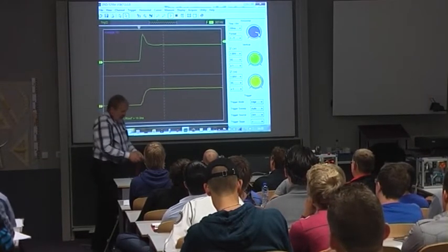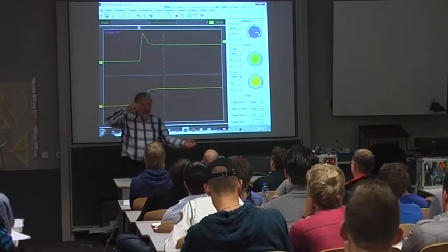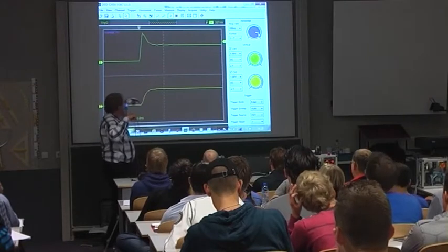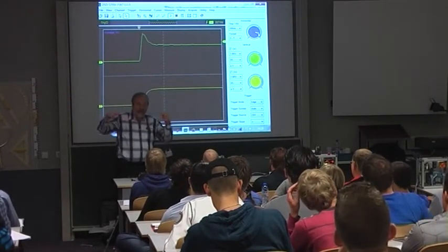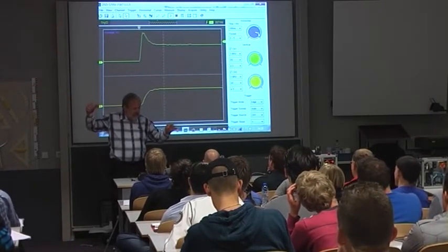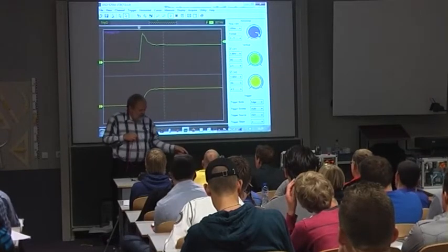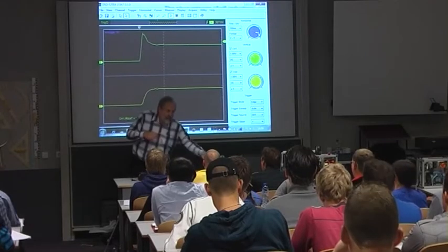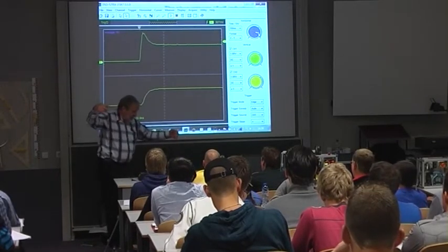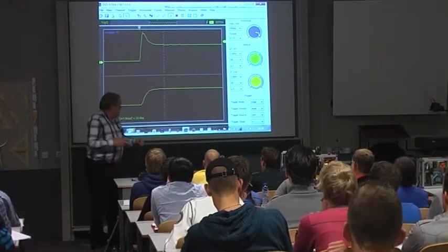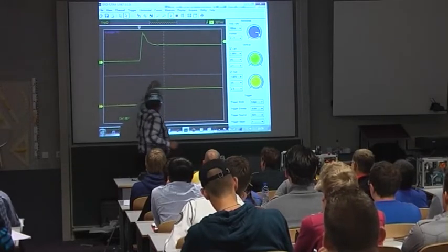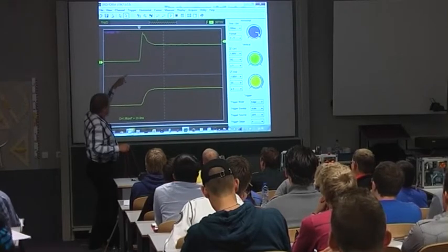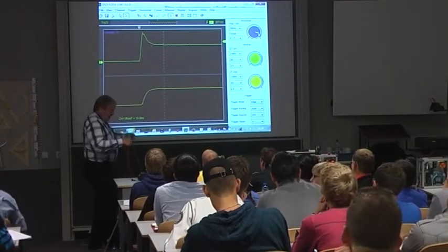Now what happens here? Okay, this square wave is in this case a 3 volt peak square wave. Put it on a wire. In the generator there's a 50 ohm resistor, and the load on my scope is also a 50 ohm resistor. So there's some current flowing here. In a stable situation, say here or here, we have half the voltage, so 1.5 volts from the 3 volts that's initially there.